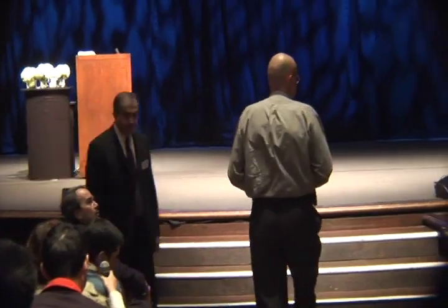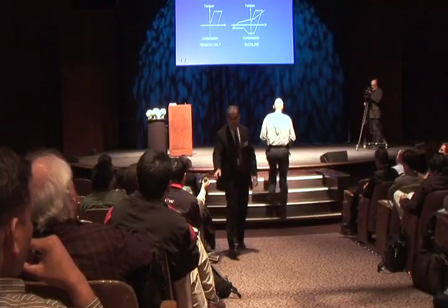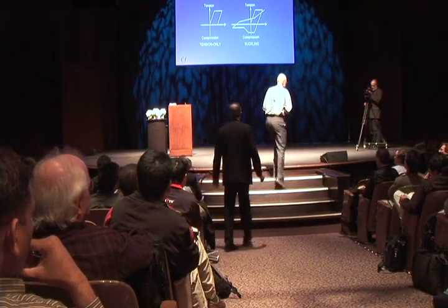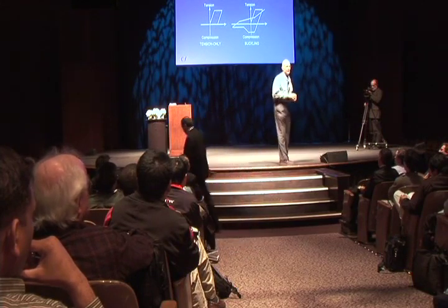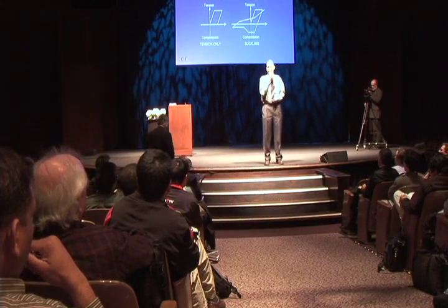So this is P delta effect. Exactly. The question was, if you have a perimeter frame structure, so you have a lot of internal gravity framing, what do you do with P delta effects? Well, the thing you do not do is model the external frame only and put on it only the loads on that external frame. That's wrong. You have to account for the P delta effect of all of the loads on the internal frame.